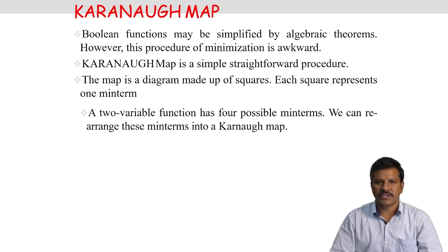If we have a Boolean function which is in either form of sum of products or product of sums, in both cases we can take the Boolean function and implement it in AND-OR-inverter form, otherwise we can design or implement a realization of these Boolean functions using NAND and NOR.